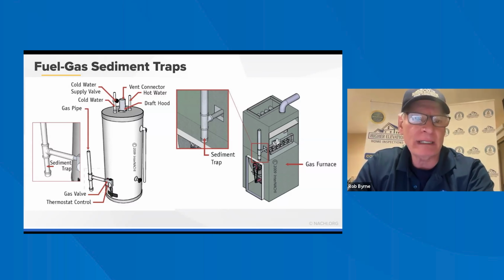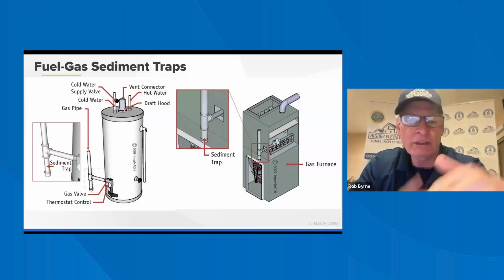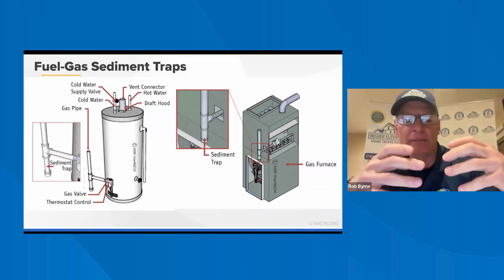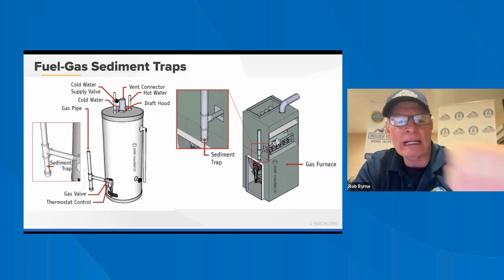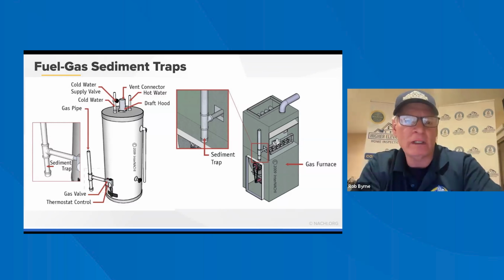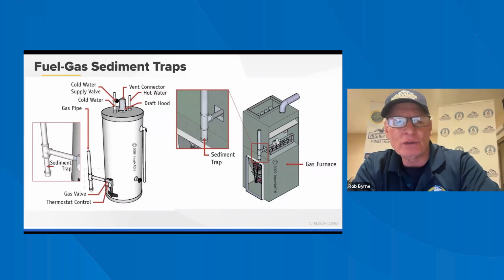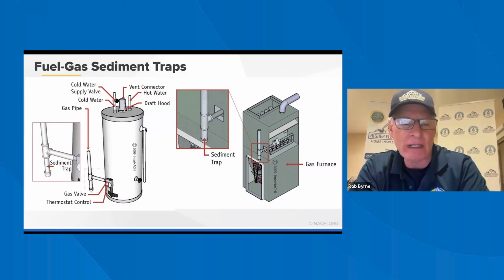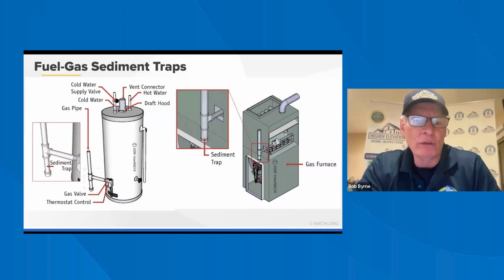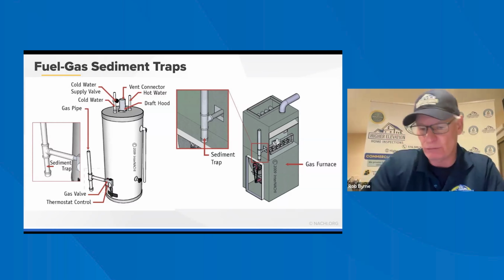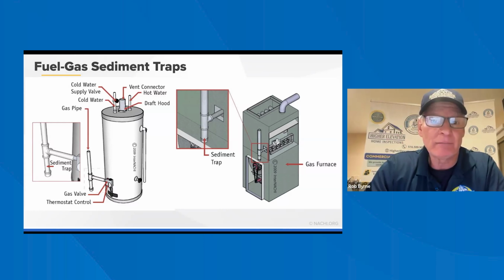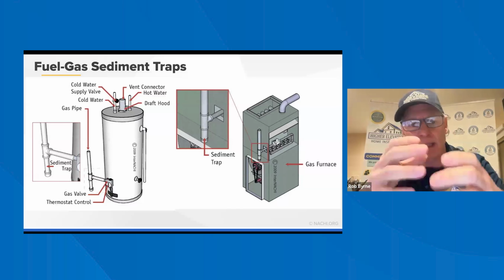Cold water supply, we talked about that earlier. There's a shutoff valve for it. So you can see how a lot of times the things we're talking about are reappearing in different aspects of the course. You want to call that out on the shutoff. If you remember when Jim was talking about backdrafting, those plastic pieces that identify hot and cold, you'll see them melted. It's backdrafting. You want to write that up. All important stuff as an inspector that you should identify and look for as you're doing your reports and your inspections. Draft hood, you've got to make sure that's lined up properly.